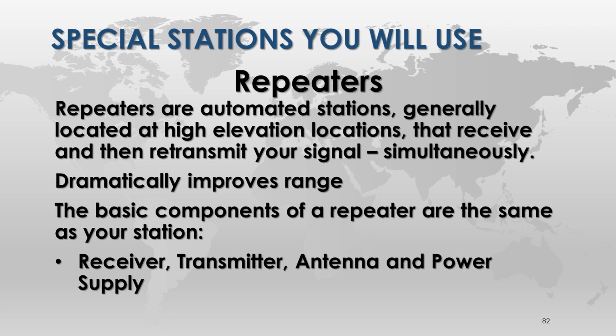And so it's tied to the radio, and then the radio spits it out to a set of cans, which we'll cover later. Those are the filters, and up the feed line to the antenna, which is sitting on top of the building. We call them cans. Yeah, filters. It keeps the receiver from getting blown out by the transmit signal when the transmit comes on. And we've got pictures of them when we get to the specifics.